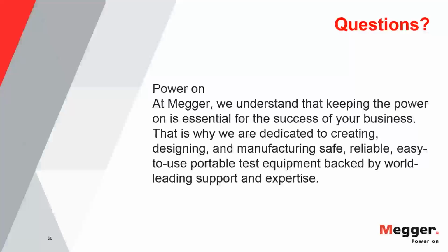No, I'm not. It's testing cables in general. The cable is a big capacitor, so we have to be able to fill that capacitor up and discharge it in the time that we have per cycle. So VLF withstand testing especially does suffer from this maximum capacity of the cable as well. When we talk about the cosine rectangular, the damped AC, we have a much higher testable capacity, even on just the basic withstand testing.